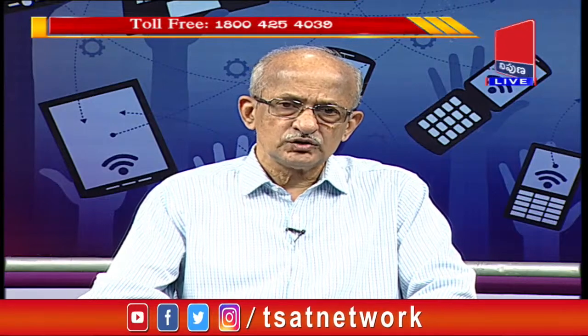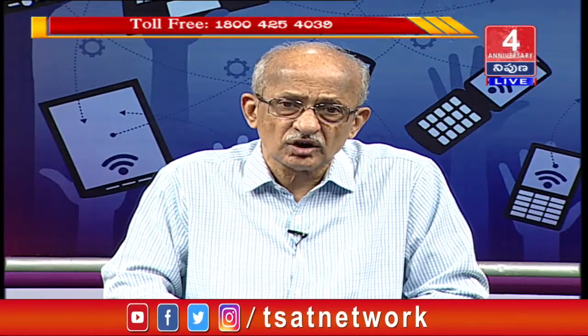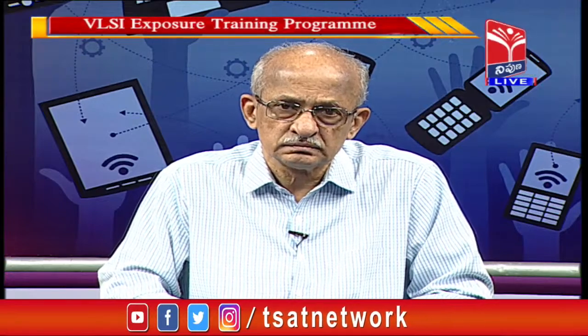Just as on a PCB you put some test points, so that you can plug in your oscilloscope over there and check whether the waveforms are coming correctly or not, similarly here also you have test points, not in the form of lugs or something like that you put on a PCB, but in terms of some logic cells, which capture some kind of data in between and internally, and then that data is made available to the response analyzer, which analyzes the response of a particular input. So that way DFT is a collection of methodologies.